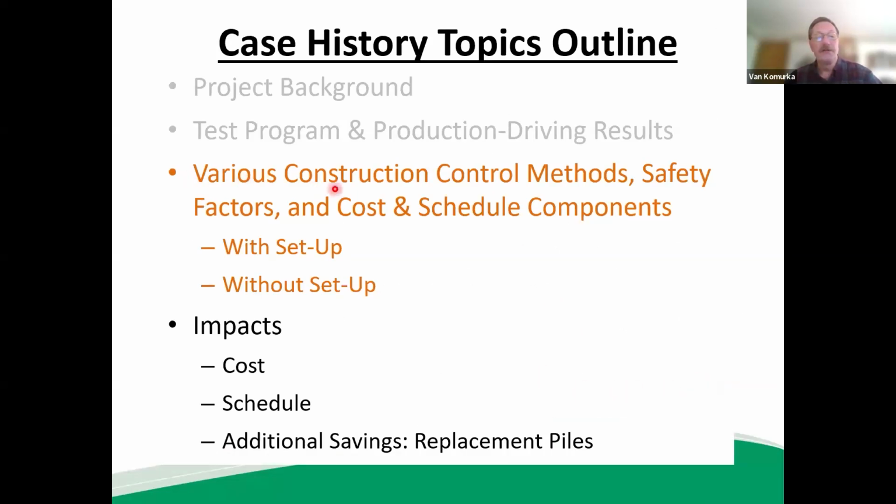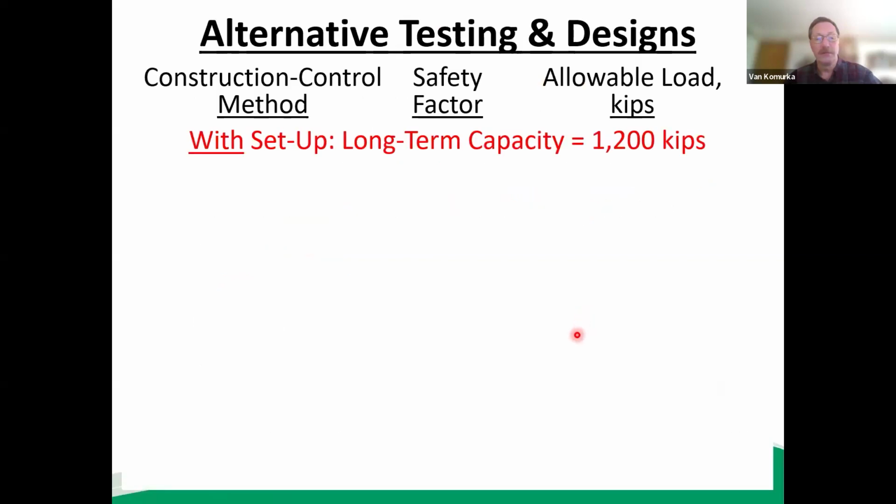When we talk about construction control methods, as we move on to our next topic, that just means how have you determined when to stop driving the pile? Why do you know that you can stop driving it? What tells you that you have satisfactory blow counts? So that's what a construction control method is.